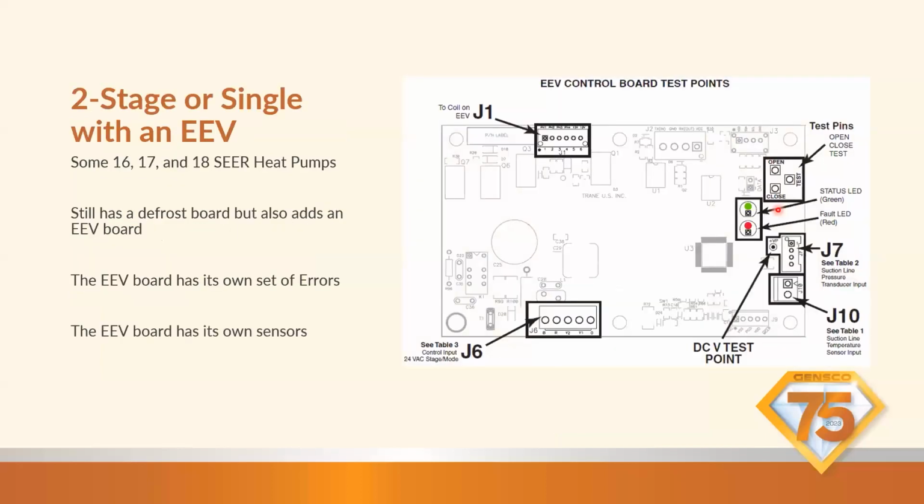All right, moving on from that defrost board, because that's it. Those are all the error codes. If you look at those, they're almost all exclusively low pressure. So low pressure in those two sensors. High pressure cutout is wired in a way where it's not going to give us an error code.